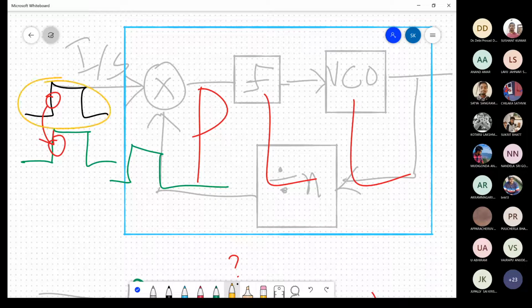You don't know anything about when it is rising, when it is falling, but you have total control over the local signal. So what you do is you adjust the beginning, the starting and the ending of the local signal till it becomes aligned with the incoming signal. So this alignment is what the phase locking is all about. Right? So this particular module locks the receiver's clock into the incoming signal's clock.